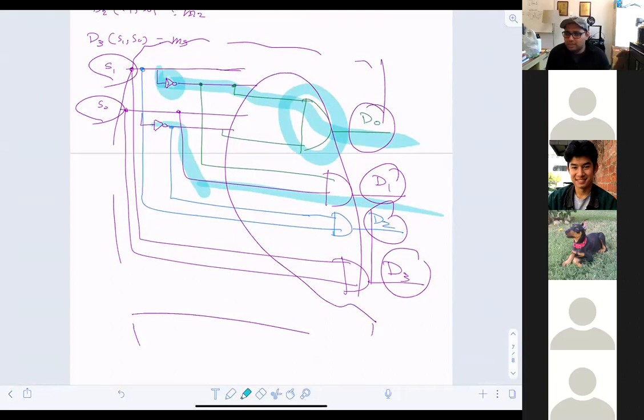What type of questions can I ask in this particular problem implemented using NAND gates? You're going to convert every single NOT gate using NAND gates, and every single AND gate with NAND gates, and the circuit will be using NAND gates, right? What if I tell you to implement it using NOR gates? You're going to do the same thing. What if I ask you with specific gates? You know the equivalency and how to change from one to the other, and you can just do the implementation. Sounds good?